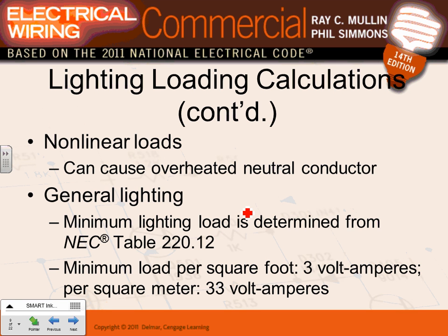Nonlinear loads. Now, Andrew, my friend, you are my friend today. I know it's Tuesday. Nonlinear load. You're going to assume the following: all your lighting loads and receptacle loads are nonlinear loads because of the computers and all the electronic equipment you're plugging in. That's our assumption. That's why, up to 225 amp panels, full neutral. Higher than that, you start derating the neutral.